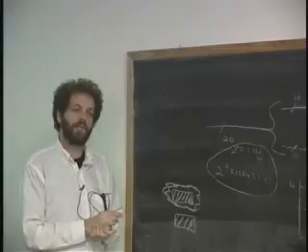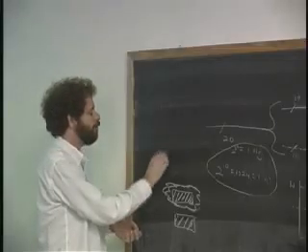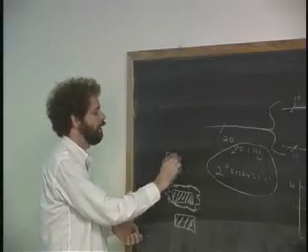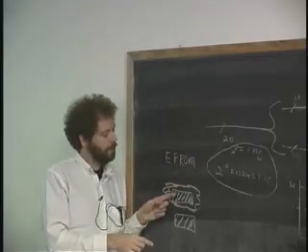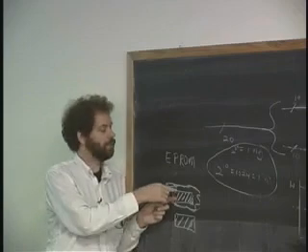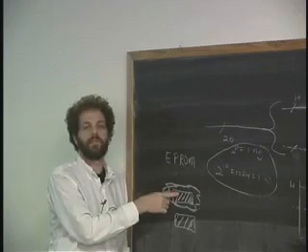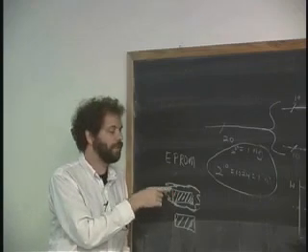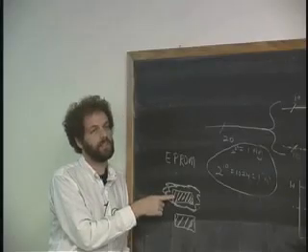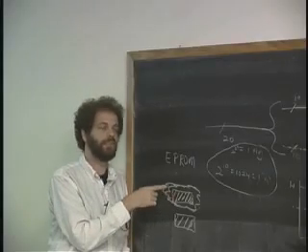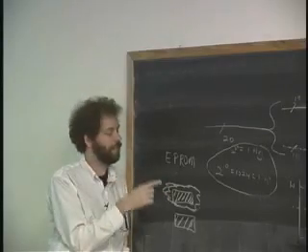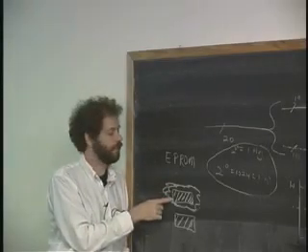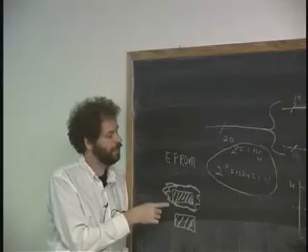But the more common one is this thing called an EEPROM, Erasable Programmable Read-Only Memory. And it works like this. The capacitor is like this, except that there's no switch hooked up to here. Okay, this stores, and because there's no switch, the switch can't leak. And because it doesn't leak, you don't need to refresh it. And the charge lasts for at least 20 years. If you get it real hot, it lasts for less.